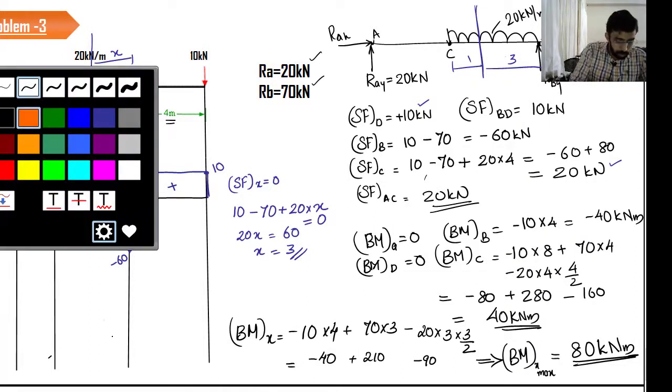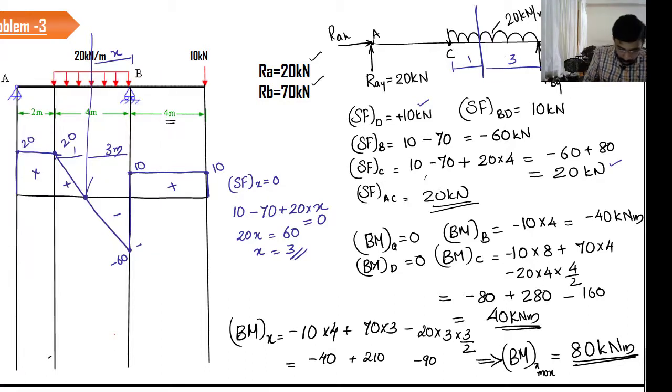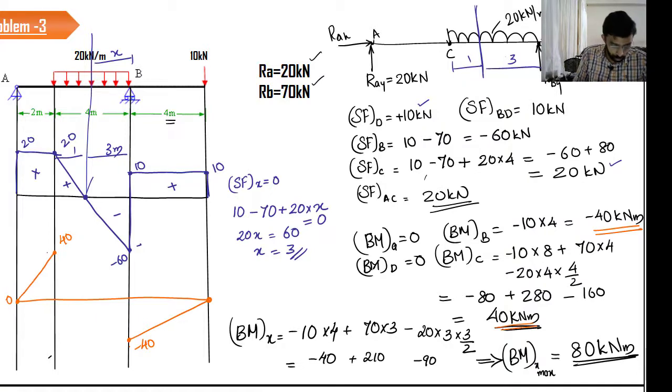Now let us plot the bending moment. So we have to take an intermediate position to draw all these things. So at this point the bending moment was 0. When we reach the point B, the value is nothing but minus 40. So it's 2 and 3. So it became plus 40. At the point A, the value is equal to 0. Now if you connect these 2 points, it will be by a horizontal straight line. These 2 points will also be connected by a horizontal straight line.